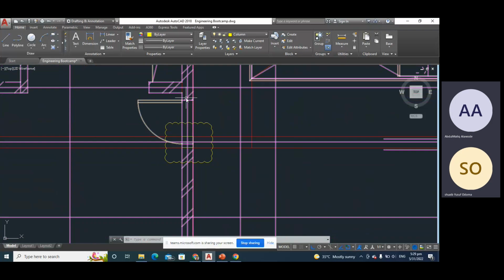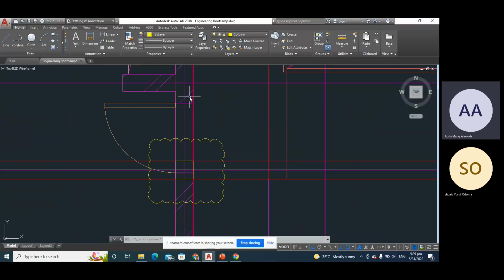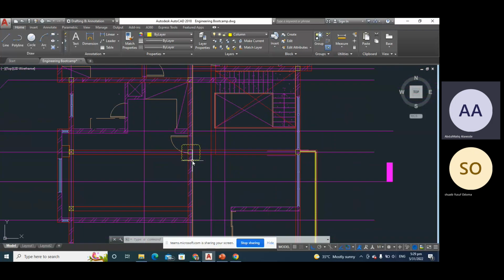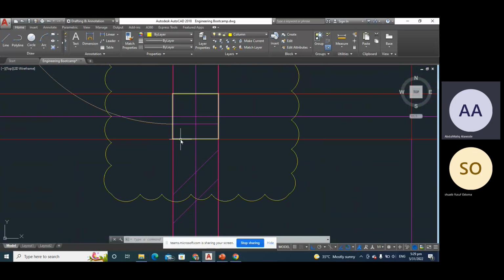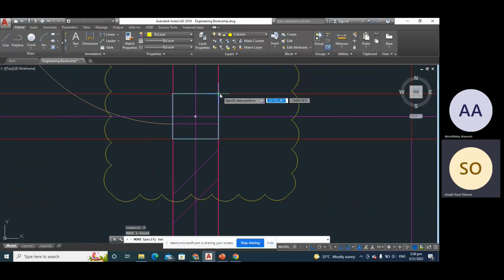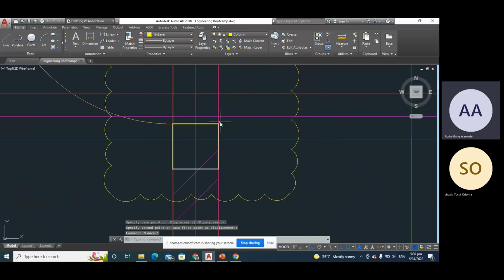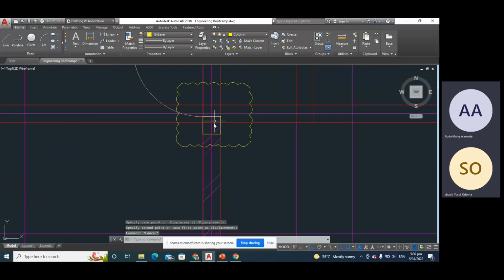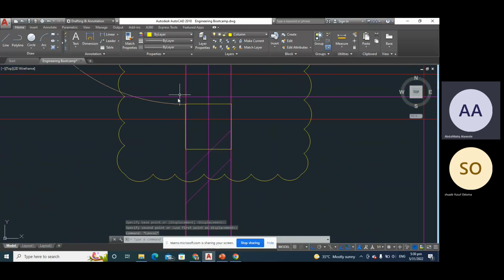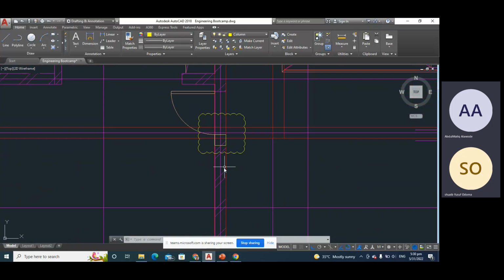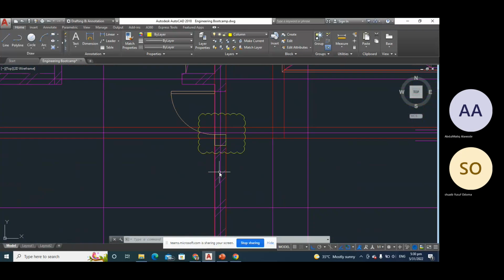Or help me shift it in a bit, because if I tend to say, okay, let me adjust this column fitting in with the door, it's going to create more movement on this beam, on this column, because having a column at the intersection of beams is preferable to having it at an offset, at an eccentricity.